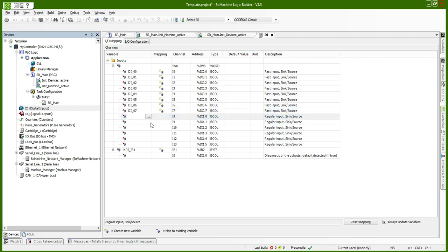Now we can either call this, it's your preference, there's no wrong answer, but typically I will change when the I/O changes. So you have ix0.7, and then it goes ix0.8, because these are obviously 8-bit words, and then we need to go into the next word. And then the other thing is that this I/O channel actually defines it as I8, or input 8.